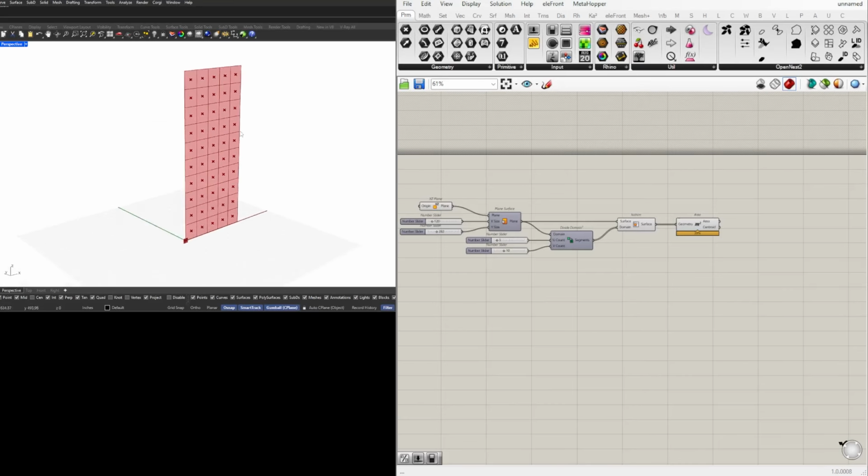So when you create a point attractor, first you need the grid of the objects that you're trying to apply the pattern to, and then you need the point, which you can do within Rhino. You can just create a point, move it up and down, and it'll react to that. Or if you want to do that parametrically, we can bring back the original surface.